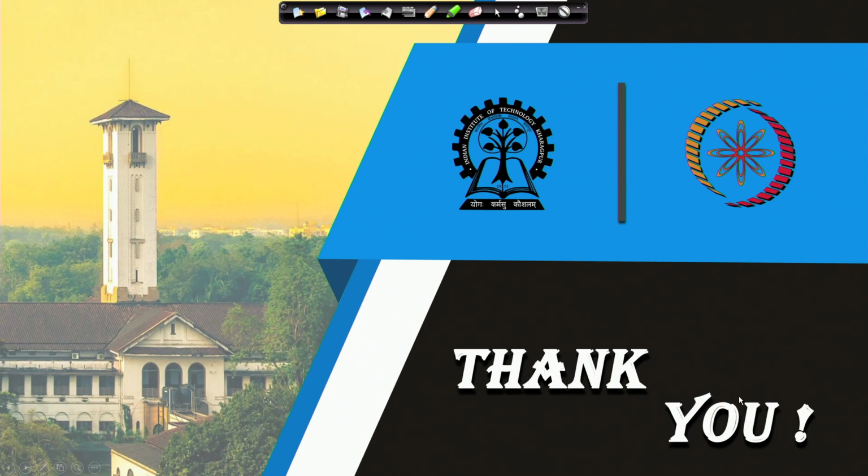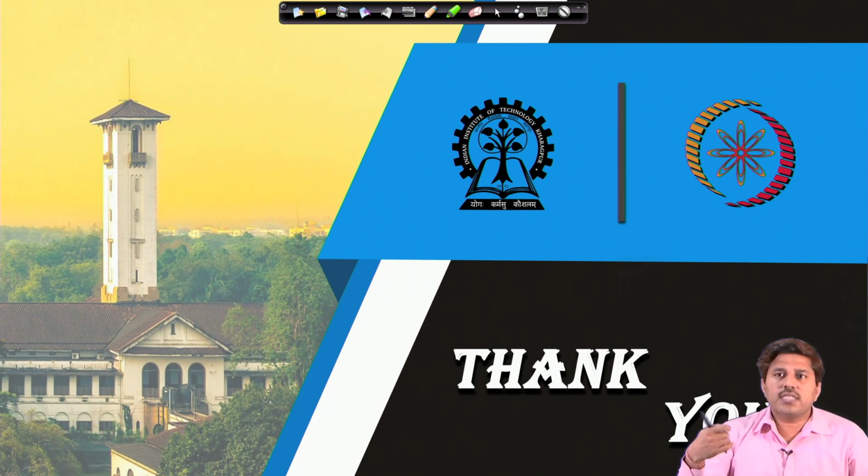So, we will conclude this discussion on the sludge. This is how the sludge is handled. And generally the sludge is not given the due attention which it should be given. In most cases, if you see the water treatment schemes, they do not even talk much about the sludge processing, but in a conventional system the collected sludge is thickened, then dewatered or dried by putting it through the sludge drying beds, and then it is usually disposed of to some landfill site or open dumping.